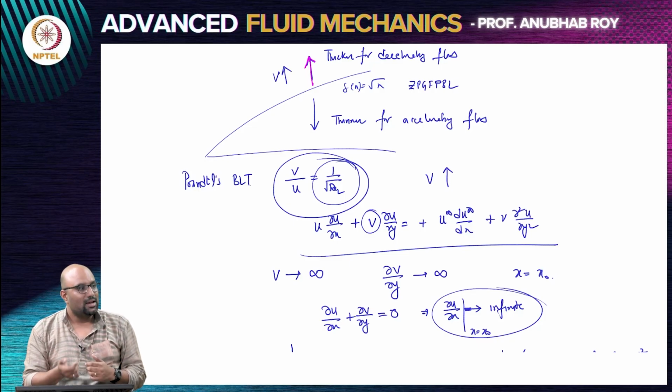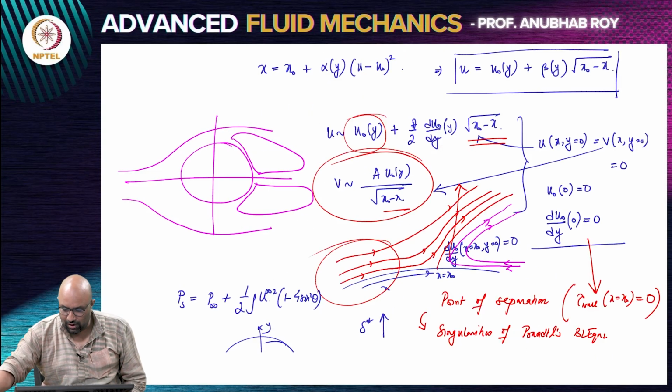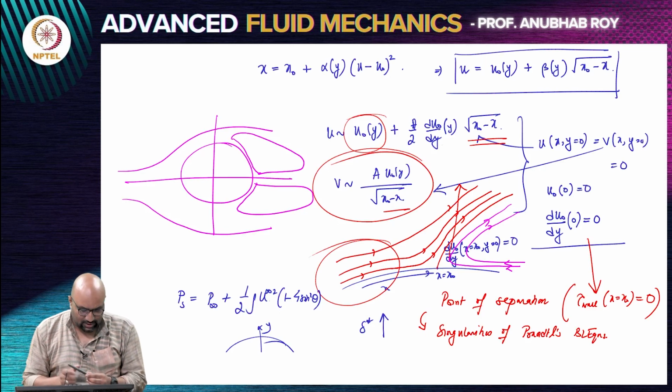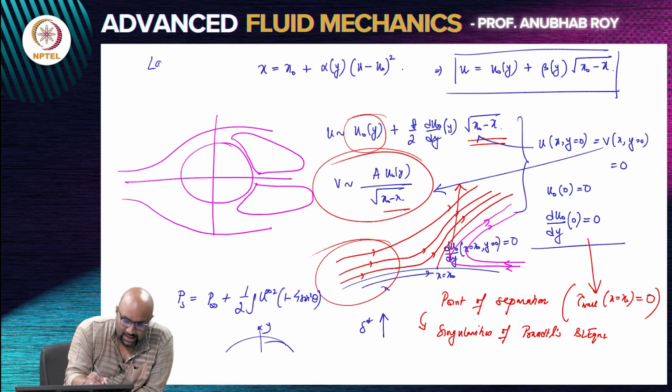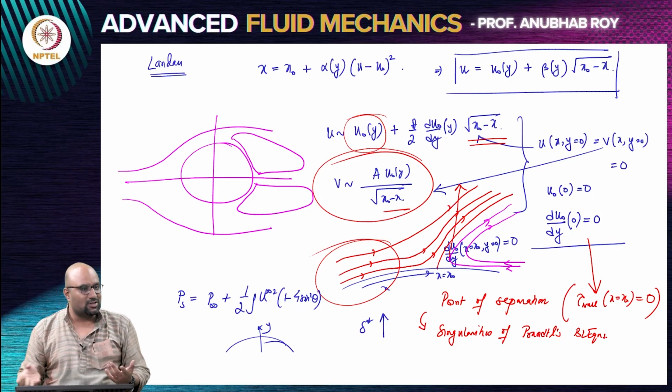And the second point is, when you have a decelerating flow at the wall, the gradient of shear stress is positive, which means that there is a possibility for the shear stress to actually vanish at the wall. And so then we tried to do this calculation, this proof for the velocity gradient going to 0 using this. The details of this were done by Landau. It's a slightly more detailed calculation, but it finally concludes what we always know or have been learning, that wall shear stress vanishing is the symptom of there being separation in the problem.